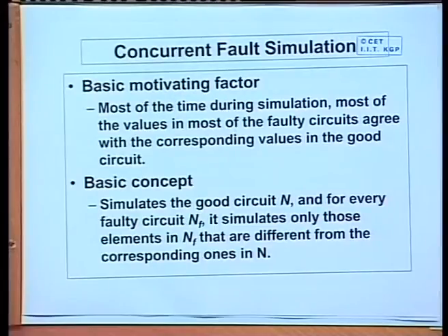So, last class we were talking about fault simulation, and if you recall, we had talked about two algorithms for fault simulation, namely the parallel fault simulation and the deductive fault simulation. So, today we will be talking about another fault simulation algorithm, namely the concurrent fault simulation, which is somewhat similar to the deductive fault simulation in the sense that here also we are maintaining a fault list and we have some mechanism of propagating the fault list, but there are some differences as compared to deductive fault simulation.